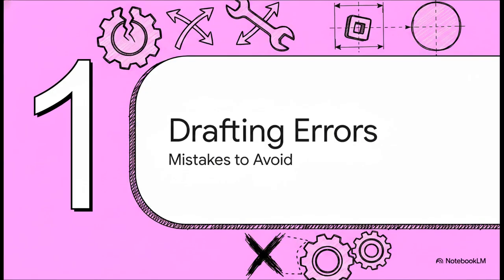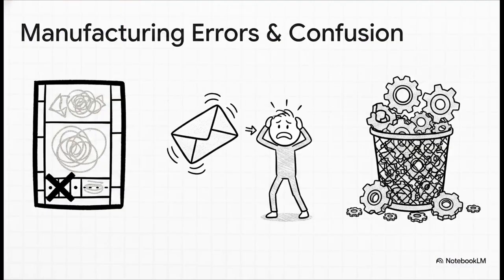Section 1. Common GD&T drafting errors. Now, according to industry data from Sigmatrix, the incorrect use of feature control frames is just a huge problem. These frames are what define the type, shape, location, and orientation of your tolerance zone. But designers often make these really simple mistakes: missing symbols, misordered modifiers, or maybe using incorrect datum references.